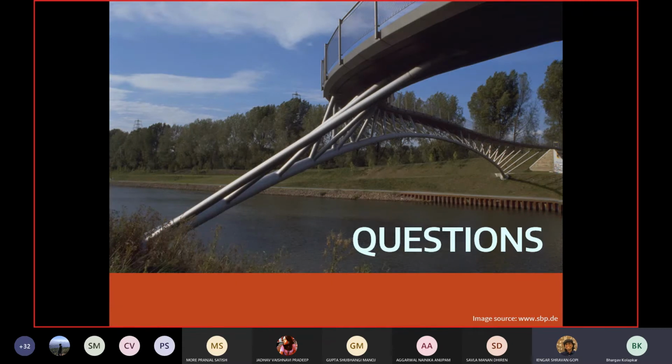Okay. So, in reinforced concrete footing, concrete has a structural function. Just like in a reinforced concrete beam, concrete and reinforcing steel act together to create a resisting moment, and also act together to resist shear. Similarly, in a footing, concrete and steel act together to resist bending moment and shear. So here concrete has a structural function.